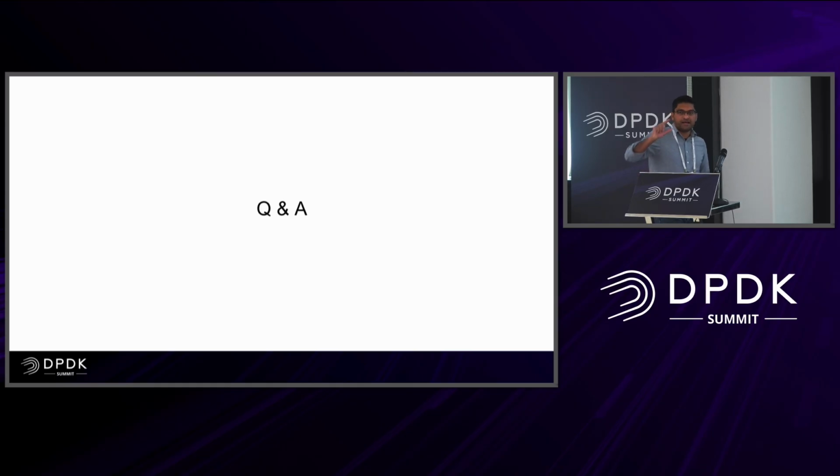So a lot of times, the difference between the ISA versions is the instructions. Let's say V8 has a set of instructions and V9 has all the instructions that were in V8 plus some extra instructions. Those extra instructions could be like SVE, SVE2, all the advanced SIMD instructions, and there are a bunch of other things, like now we saw some RISC-V wait-for-event kind of things. All those things we have in ARM as well in V9, but in V8 you may not find those things.